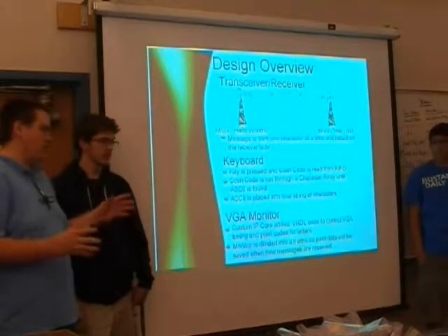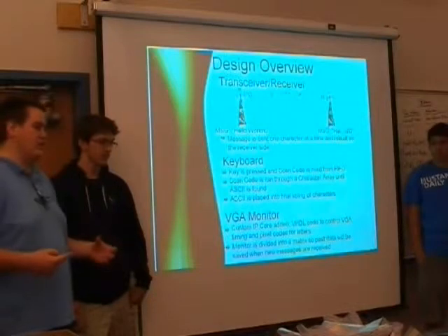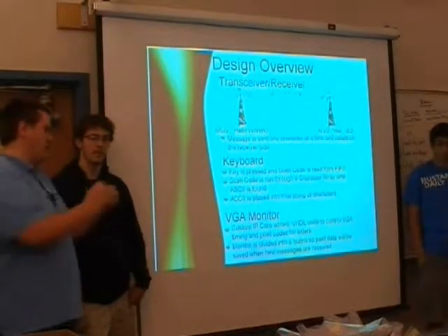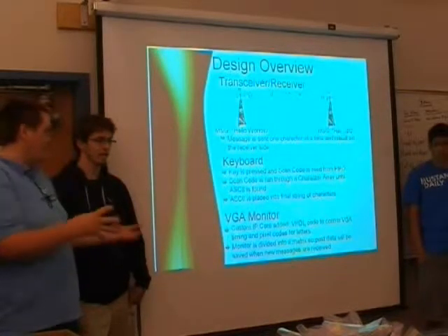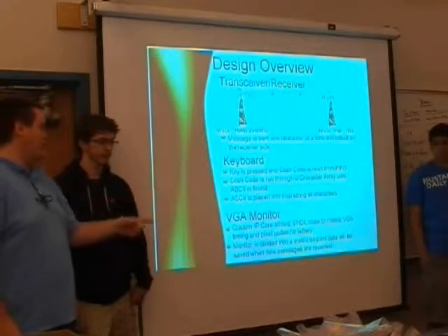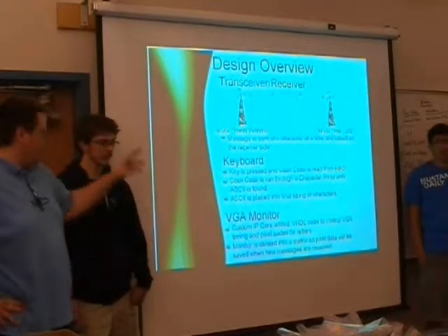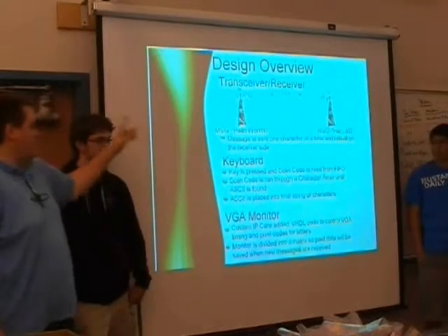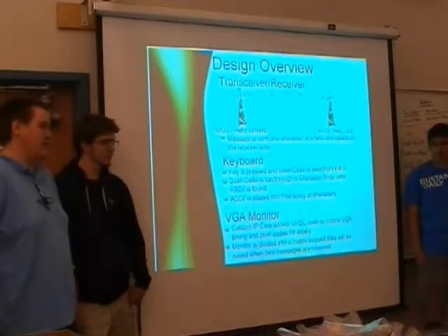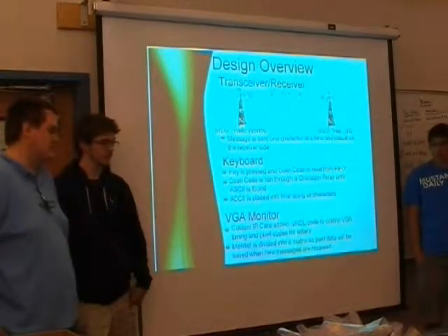It gets packaged up with a lot of address bits, a preamble, and some cyclic redundancy checks on the end of it. Gets all dumped into a payload, which is then transmitted to the other side, ripped apart, and they find the byte we want to display, throws it up on the monitor, and then checks for another byte to come in. And as you create these bytes of data and send them over, we decided that it would be easier just to send them 1 byte at a time rather than to deal with a long single payload.